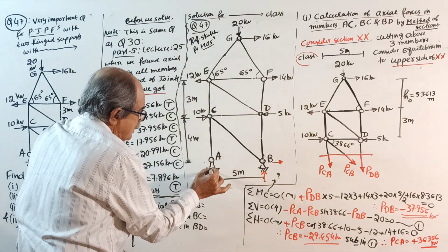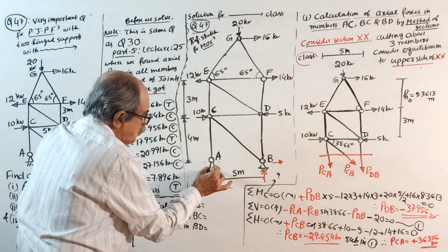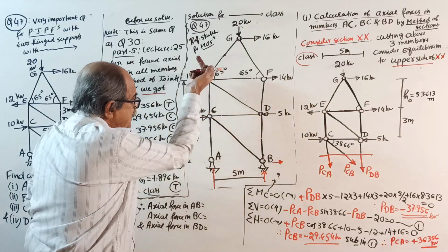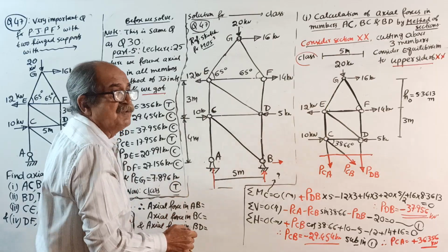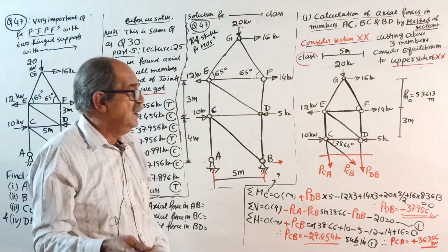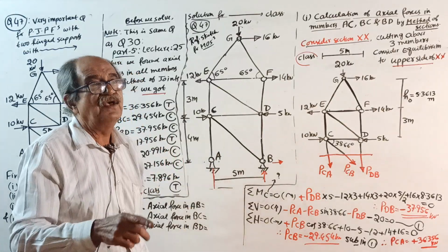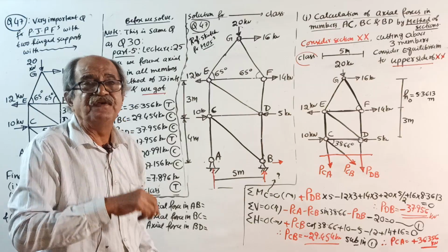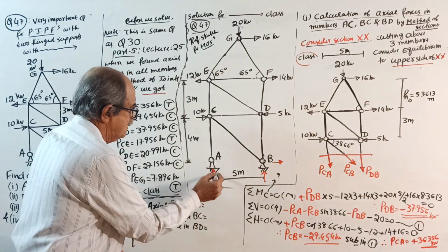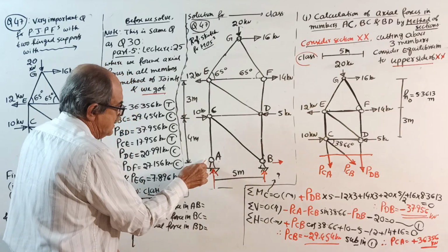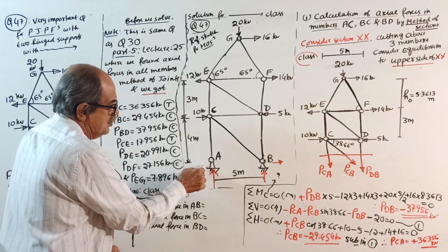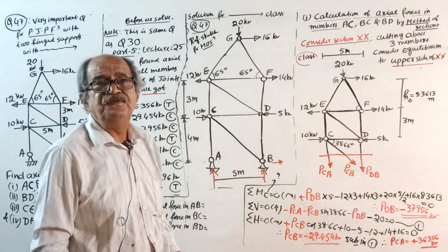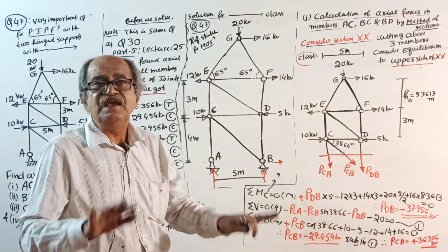Therefore, even though it is a hinge, there is only one reaction, and the line of action of that reaction is along the member connected to it. By chance, even if you take a reaction here, when you take sigma as 0, this will become 0. Now tell me, sir, then this support, even though it's a hinge, is as good as a roller. Yes, correct.